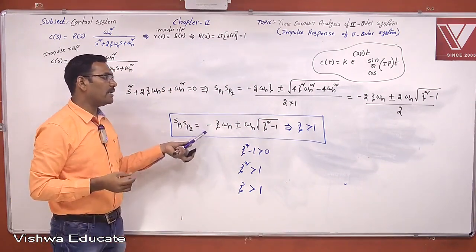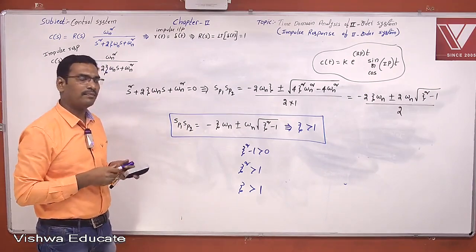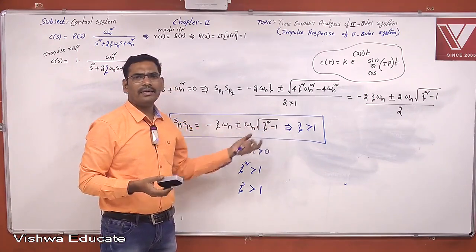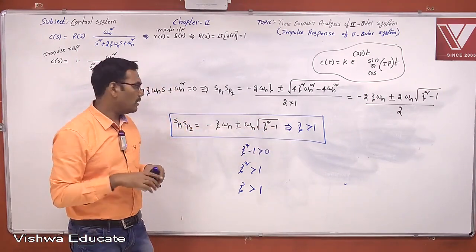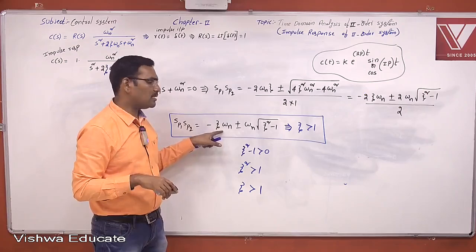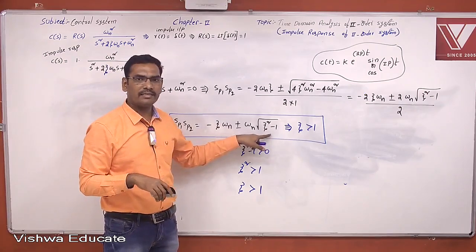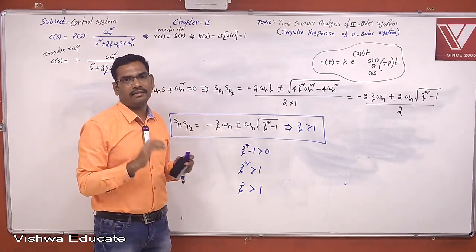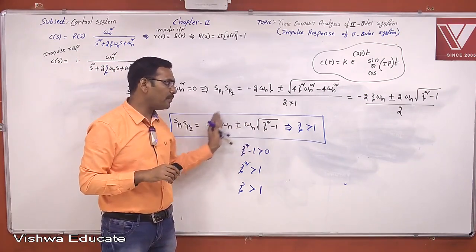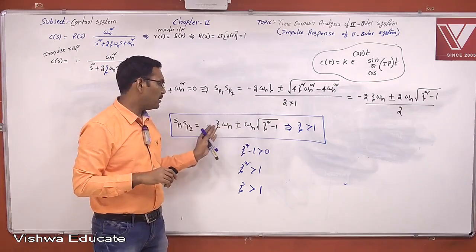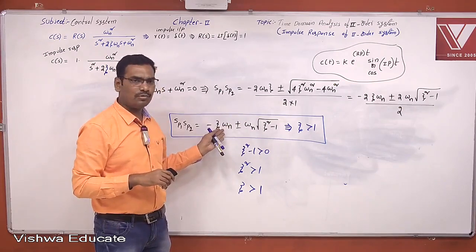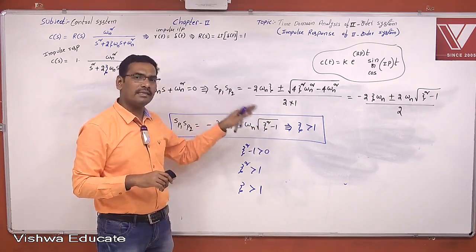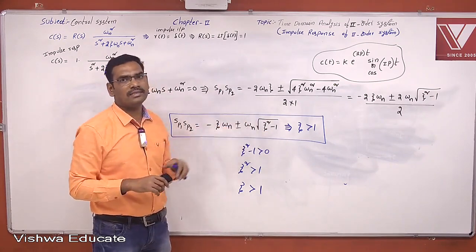Now this should be treated as case 3, damping factor zeta greater than 1. But now you see, don't say this is real part and this is imaginary part. Real part and imaginary part are separated with the j term. This is totally a real part. Assume this is minus 2 plus 3 or minus 2 minus 3 like that. So totally this is a real part.